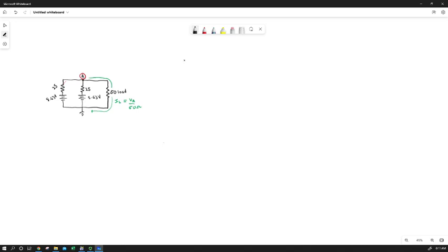So we're going to use superposition to get I load, and maybe we'll get VA. What we really want to know is I load for these imperfect sources. How much load current can we actually get, and how much? We already know the answer from our simulation, but we're really interested in how much benefit we get from having those 2 parallel sources, given the fact that we've got some internal resistance.